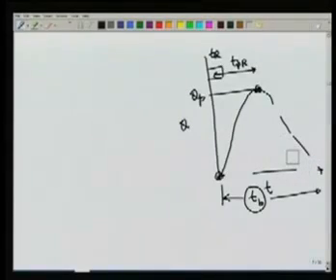There are some other parameters, for example, the width of the unit hydrograph at some location can be given. In this case, suppose QP is the peak flow, we can find out what will be the width of the unit hydrograph at 50% of QP and call this W50.